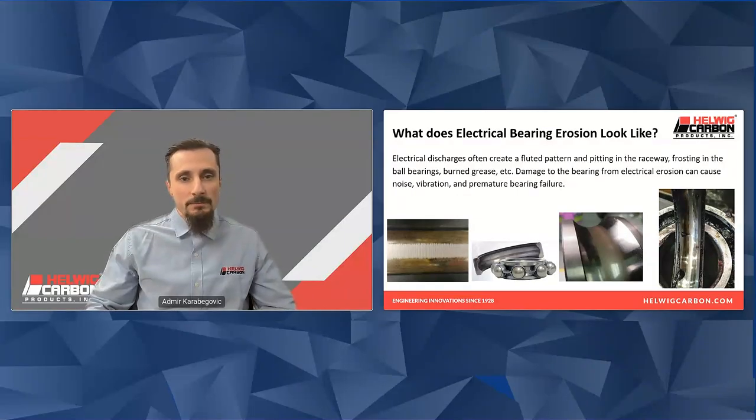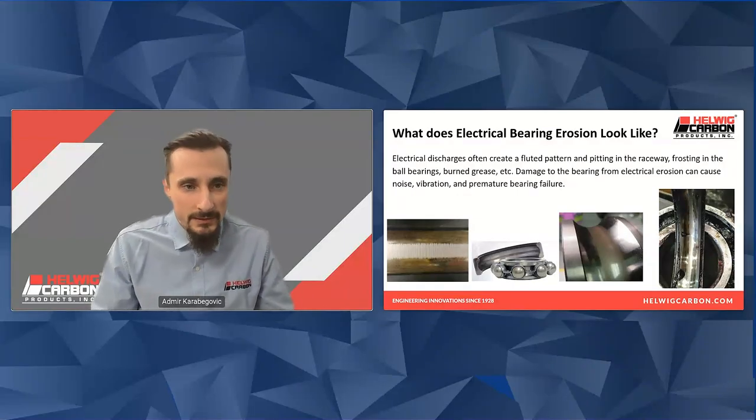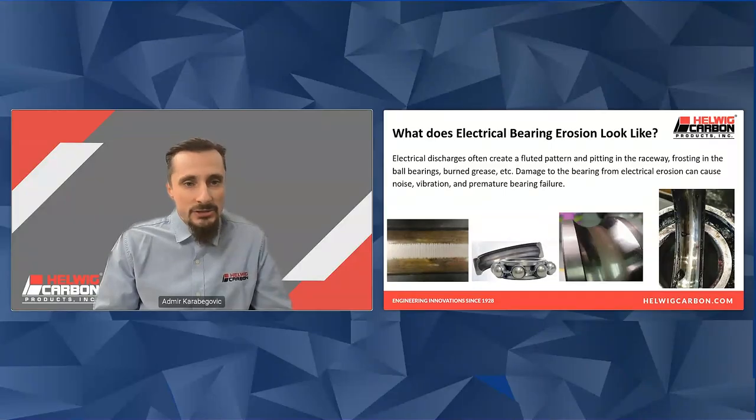So what does electric bearing erosion look like? Electrical discharges often create a fluted pattern and pitting in the raceway, frosting in the ball bearings, and burnt grease. Damage to the bearing from electrical erosion can cause noise, vibration, and premature bearing failure.